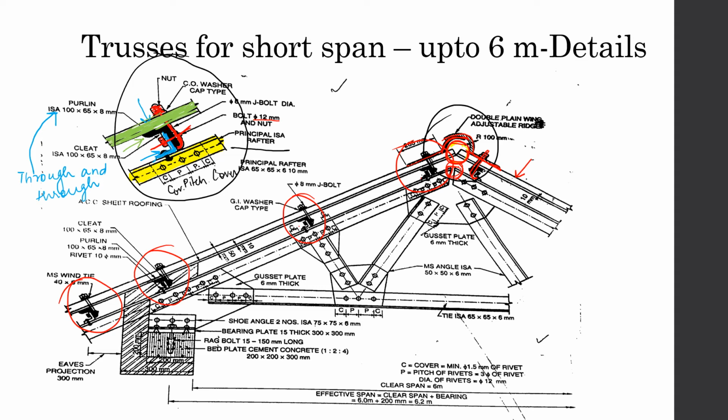So this is how they ensure that the ridge is covered with a ridge piece and that water is unable to come in. Also this overlapping is important so that it does not leave its place, and it maintains the structure which is being built, and it does not move around very much. And this also, like the purlins, goes through and through till the length of the roofing that has been provided.